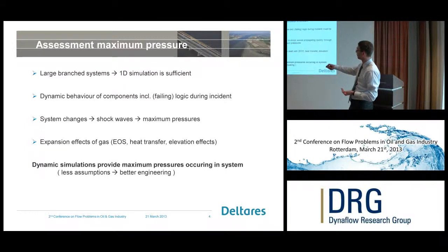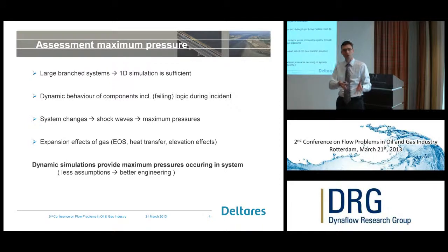Further, if you do have a dynamic behavior of your model, that may result in changes in the system, and those changes may lead to shock waves. They're quite comparable with water hammer shock waves, but if you go to gas systems, then the density will change because you've got compressible flows. So that's the fourth bullet. Expansion effects of gas must be taken into account.